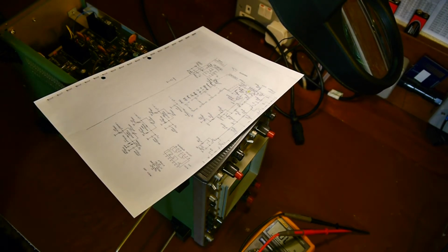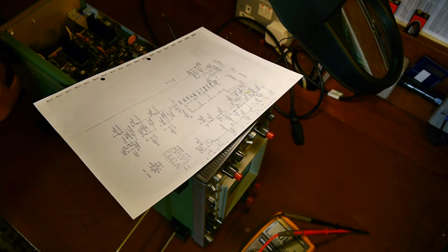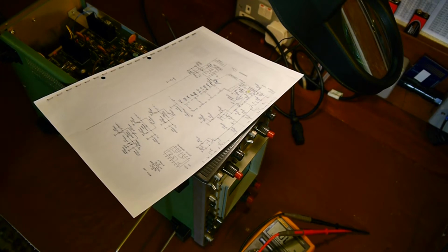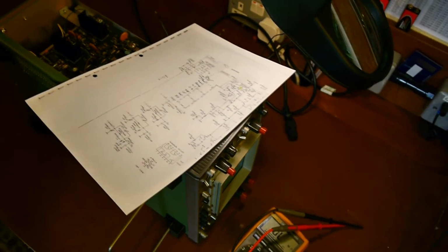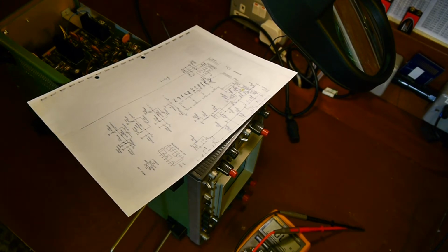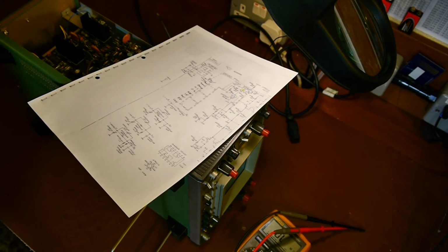I'm wondering if maybe the next thing to do is actually do some signal tracing. Yeah, maybe that would be the correct thing to do. It's not like we're short of oscilloscopes, is it? Let's do some signal tracing. That's going to be good for a laugh. And the great thing about oscilloscopes is, because we've got channel 1 and channel 2, we have a good channel to do our comparison again. So let's see if we can trace the signal through from the input and see where it appears to be going astray.